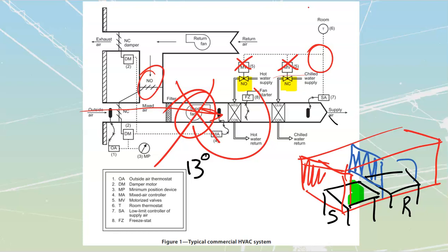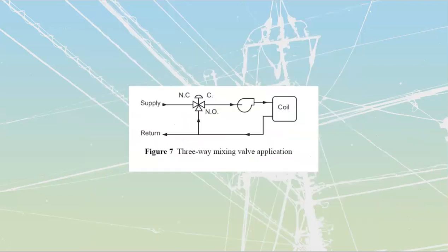Heat pumps, we've talked about that one as well. That's one of the last sections inside of your module over there. And then the last little blurb is one paragraph long, and it says control circuit wiring. Highlight that. They're often going to be low voltage and low current, which means that they're usually going to be a Class 2 circuit. We're going to look at that in code this week. Class 2 circuits being limited to 100 VA of total power. All right, that covers us off for commercial HVAC components. On we go.